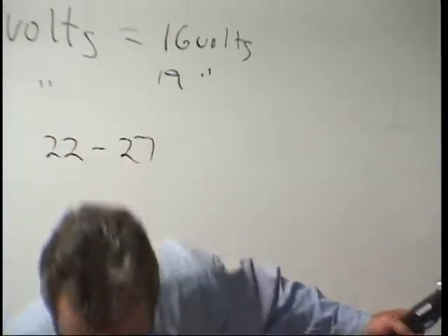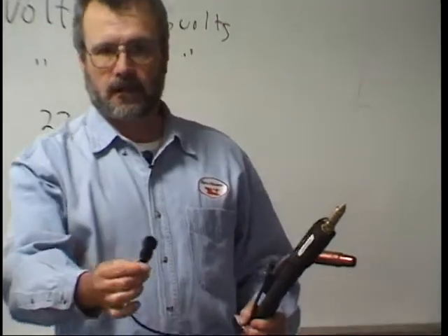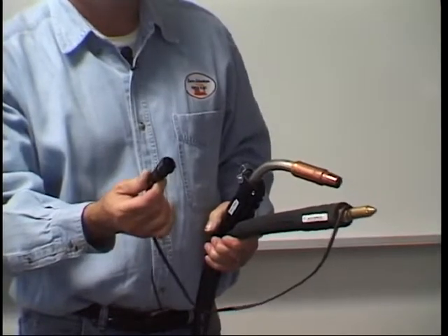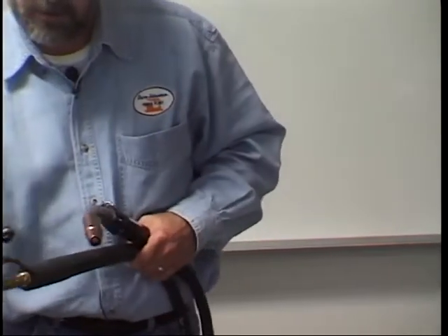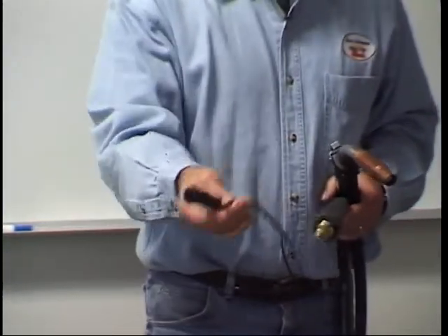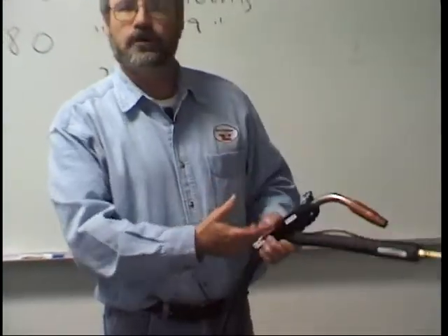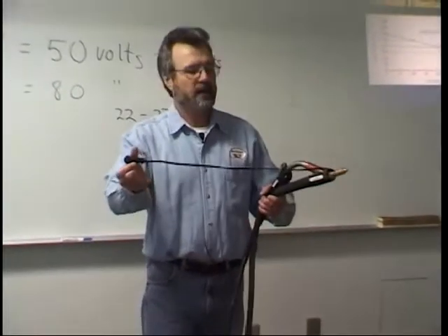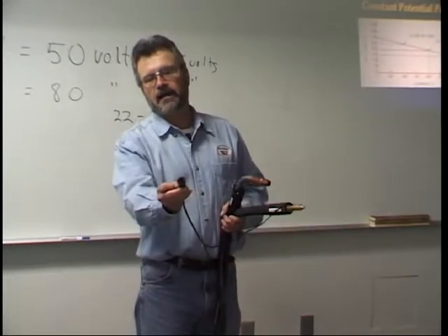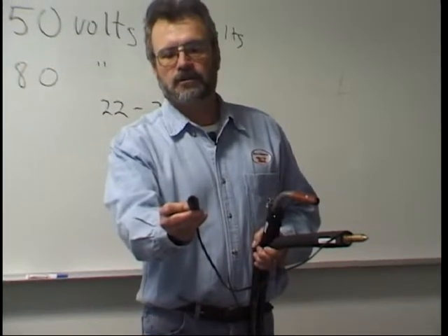And that trigger is connected to the power supply through this. And the power supplies that you're using now, this is really a great design. It's a big improvement over what they used to have. You can see it's hardwired in here. But there's only 2 leads. If I wanted to, I could take and short these out. I could cut this thing, bare those wires, touch them together, and everything would start running because that's all the trigger does. It just closes the circuit. And that's why they only have 2 leads, an in and an out. Completes the circuit. And you can see, you can't really pan in there to see that, but there's 2 little probes there, and that's all that you have to complete the circuit.